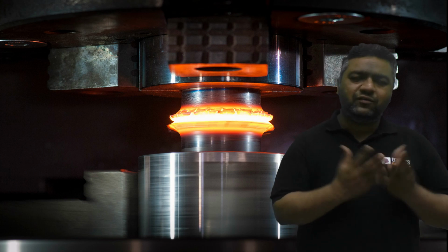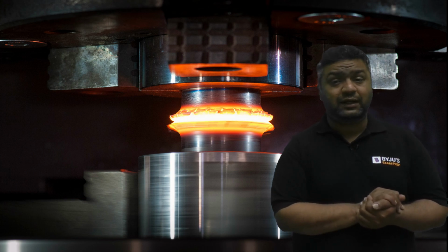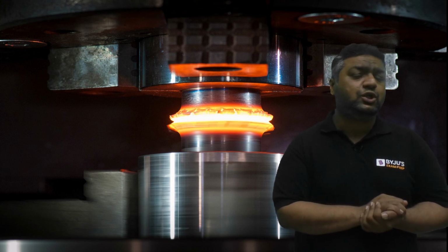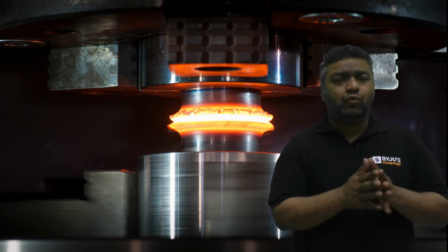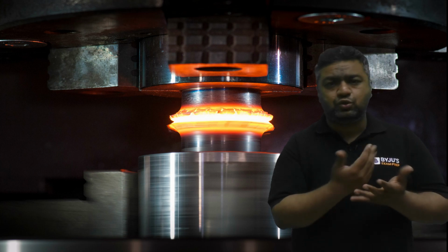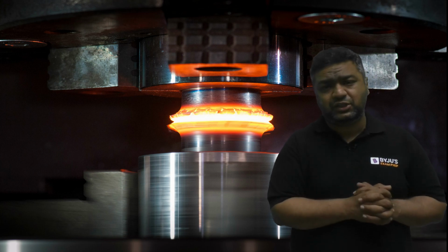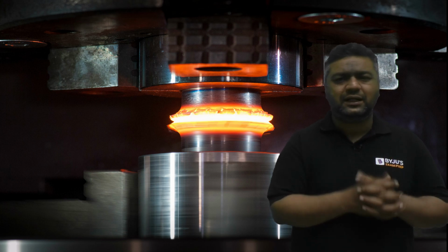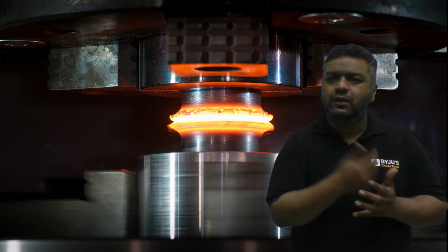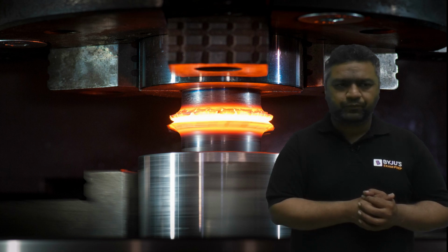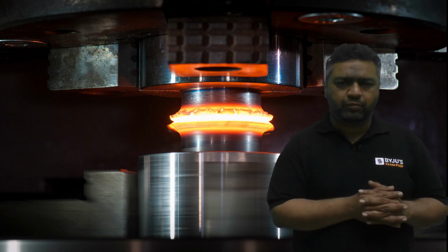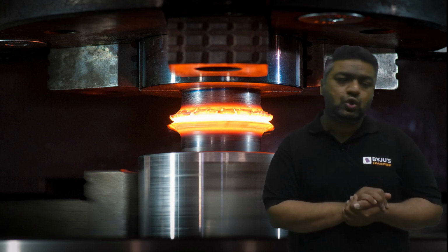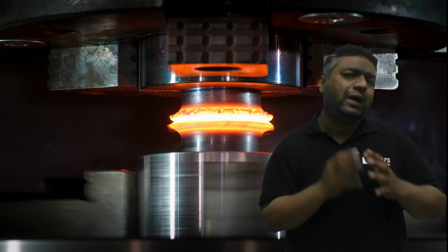So guys, when we are talking about solid state welding, as the name suggests, melting of the workpiece does not happen. So when melting does not happen, what temperature range are we reaching? It is around 40% to 50%, or you can say 45%, of the melting point temperature. Then how will the weld be performed? The weld will be performed with the help of a diffusion process, so one material gets diffused into the other.